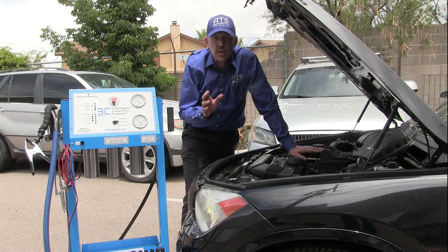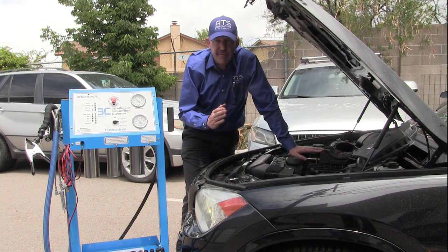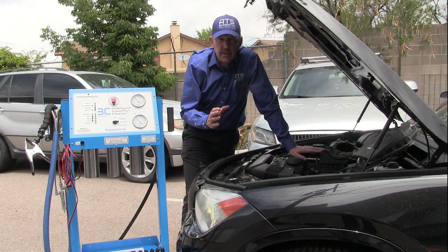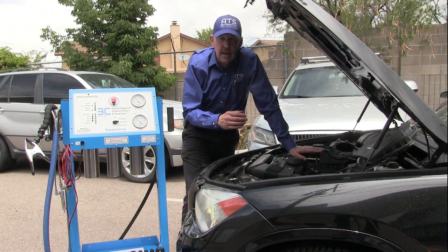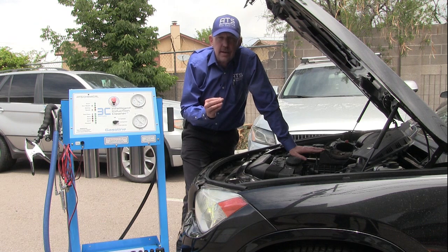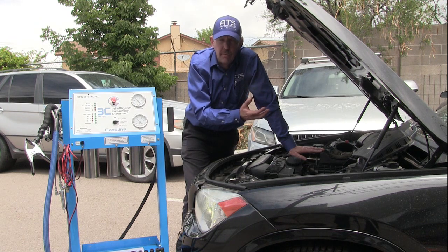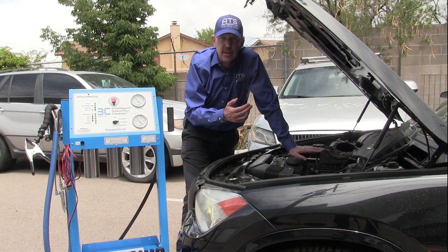Now this is one of the most important things of the whole cleaning process. You must find a common vacuum port that's behind the throttle blade, preferably the purge or the PCV. We never want to put the chemical into an end port or somewhere that's not centrally located. If we use a purge or a PCV, the engineers have taken the purge system, which is taking fuel vapor, hydrocarbons, through a vacuum system, and it's being put into the engine.